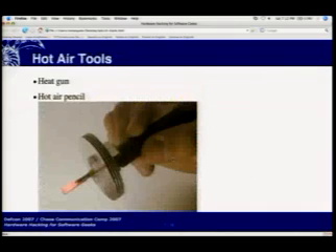Cool. This is a home-built hot air pencil. You can get hot air guns pretty easily. They're temperature controlled, usually 600 to, say, 1,600 degree stream of air, capable of melting solder. This is useful when you're trying to rework a surface mount board. You just apply the heat, heat up all the pins of the chip at once, and you can just lift it off with tweezers, which is a lot better than trying to get each pin one at a time with a soldering iron.